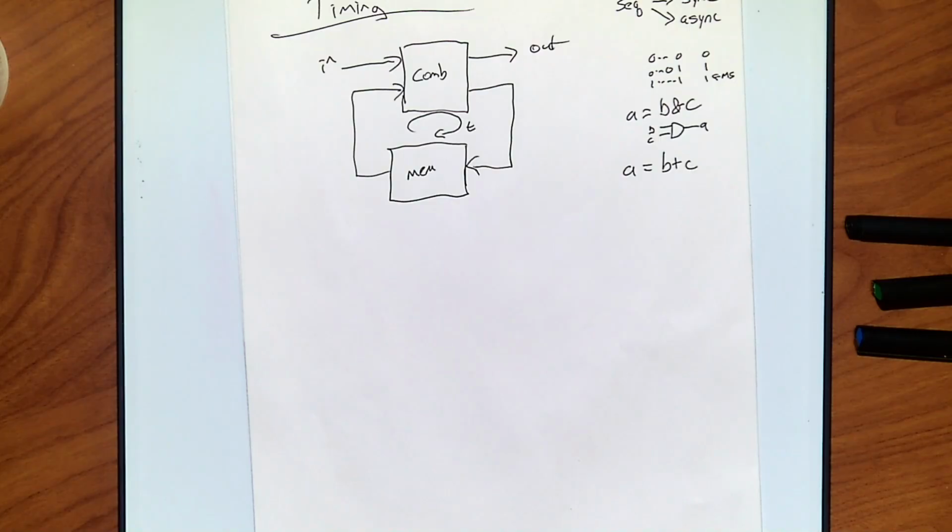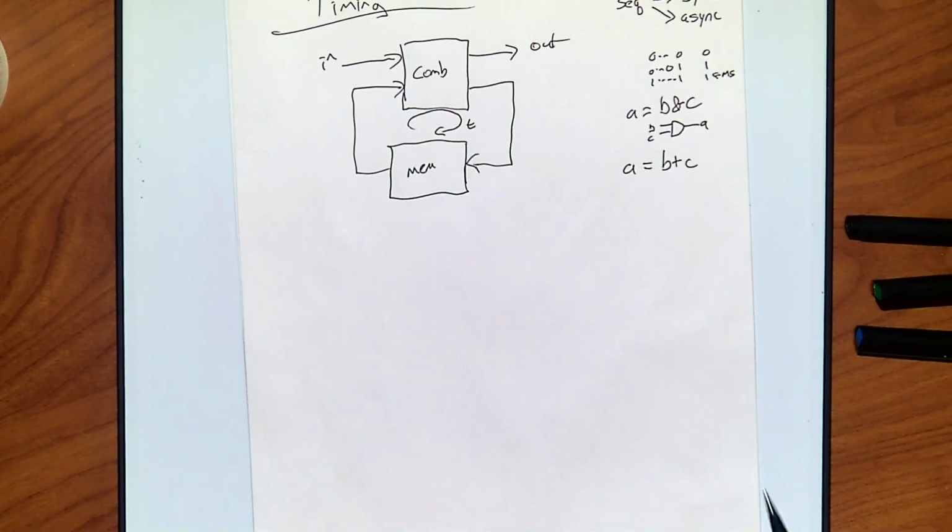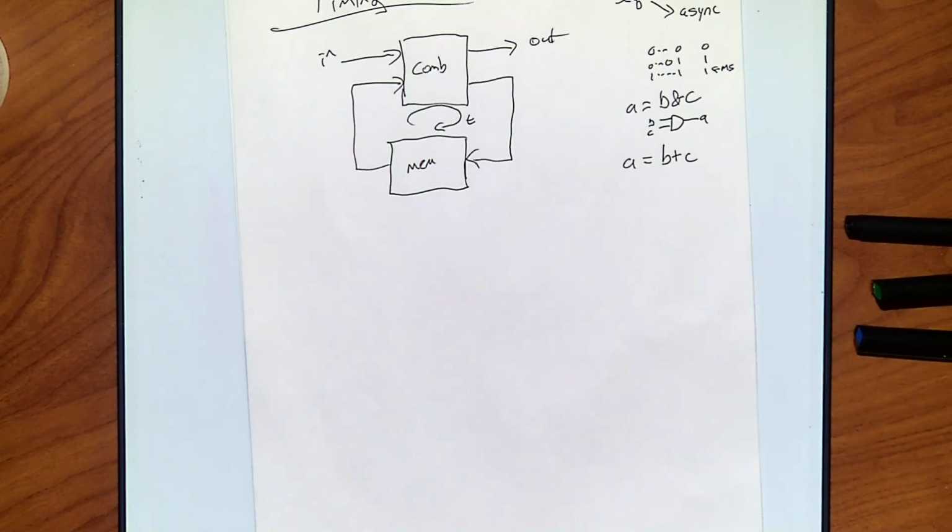Bitwise is pretty much always what we want if you're building hardware. There is a small chance you could be doing a logical test, in which case you do need logical. If it's the condition of an if statement, you probably do want logical at that point. But in most cases, if you're just trying to build something and do something on it, then you probably need bitwise. So that's some general rules on this. But anyway, you can get this. What is this? Can I look at addition, or multiplication, and infer a circuit?